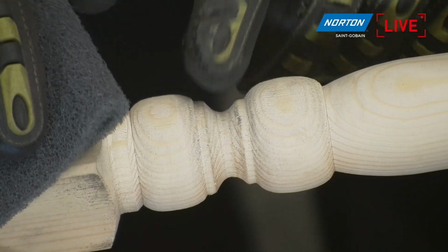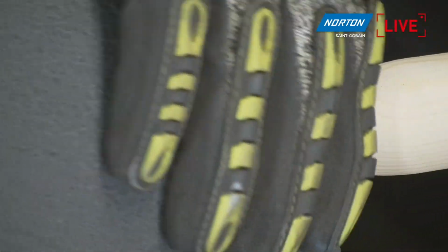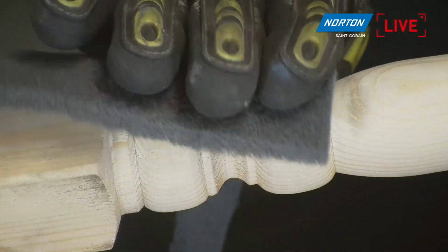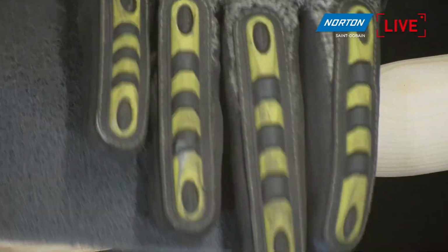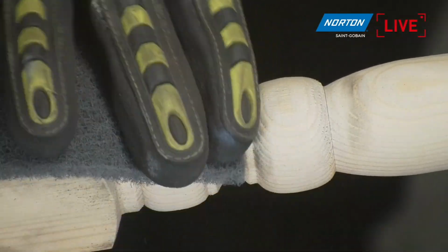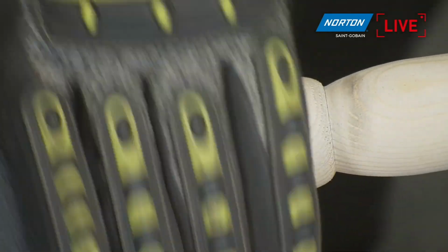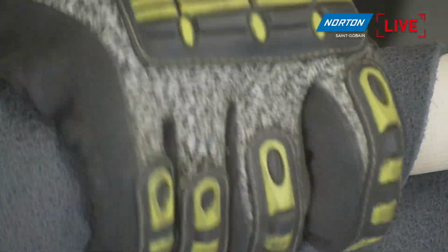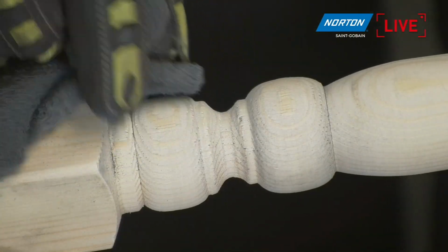And again, sandpaper is going to be really tricky to get inside these areas, but the hand pads are absolutely perfect for that, just to smooth these down before you paint. If you don't do that, you'll see all of these little witnesses of the machining marks from the wood tool when this was shaped on the machine, and it will not look so nice. So you can rub that around there and get a really nice flat finish on the wood, really easy with the silicon carbide.